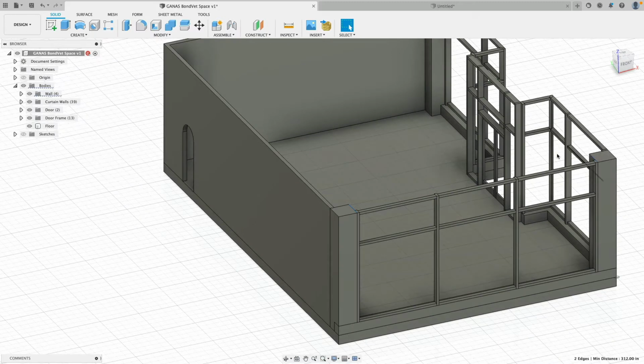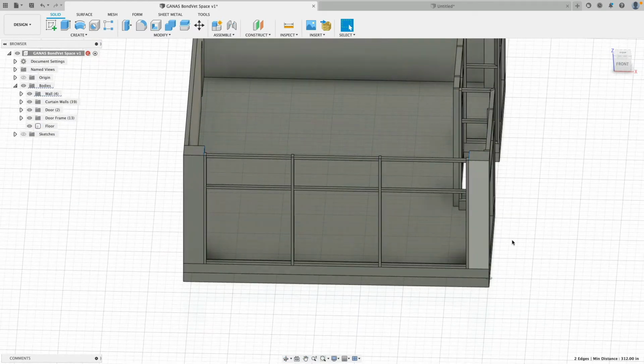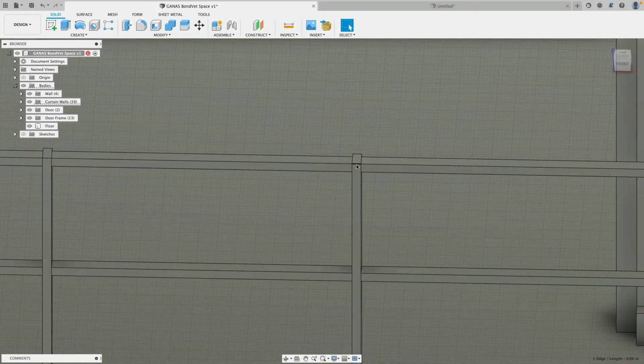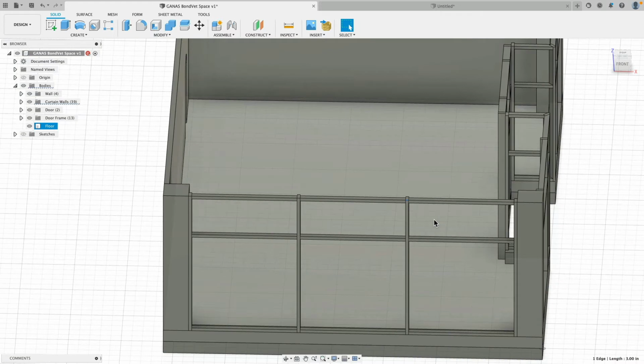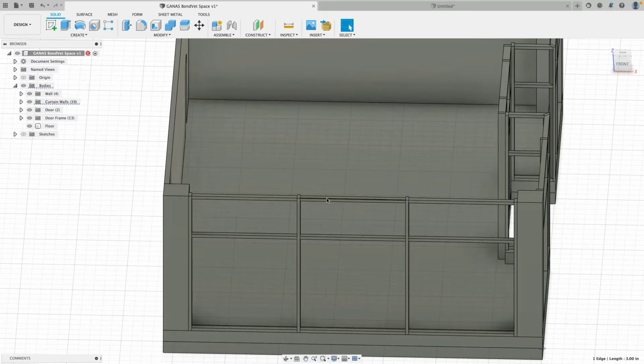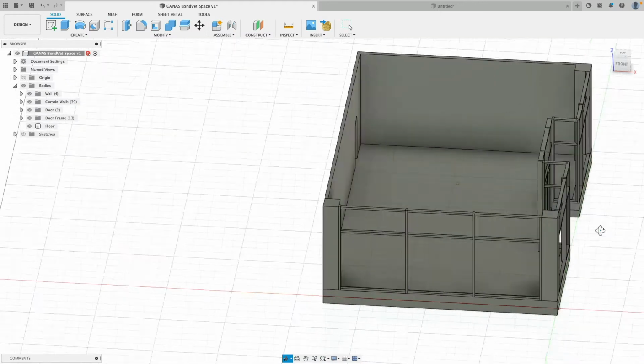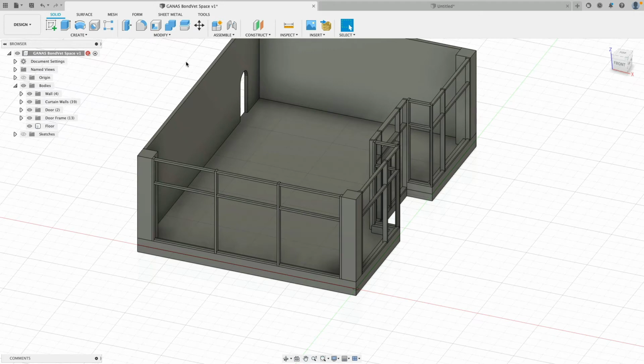I took a measurement between these two lines, which is 312 inches. And I have 1, 2, 3, 4 vertical elements, which have a width of 3 inches. And basically all these 4 together, it's basically 3 multiplied by 4, so 12 inches. We will remove, and then we basically have the leftover distance, which can then be divided by 3. And then we have exactly the amount of material or length we need. Very good. So how did I model this?